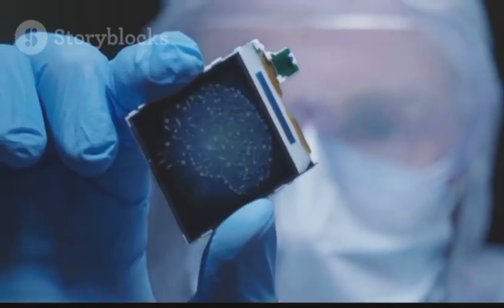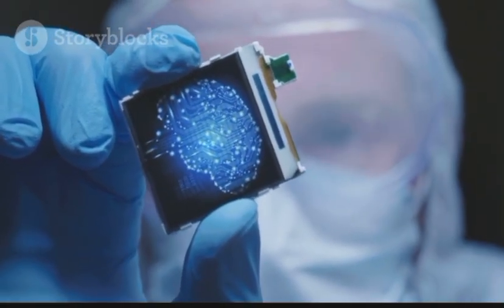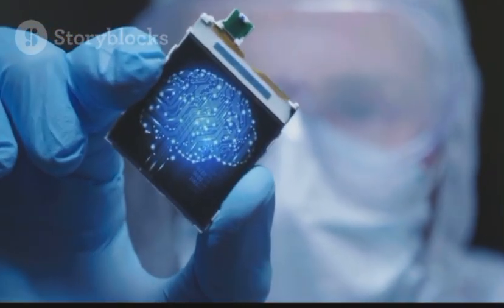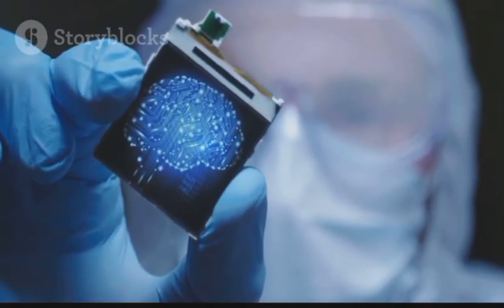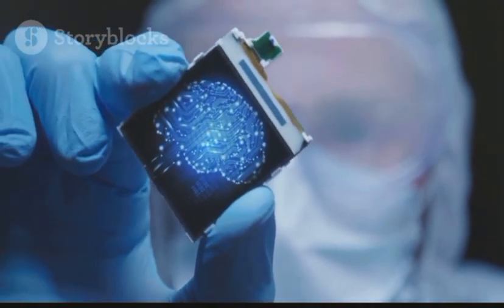This pattern guides where we add N-type and P-type elements, and where we etch tiny pathways for electrical current. This layering process is repeated over and over, building up billions of transistors and their connections. Finally, the wafer is cut into hundreds of individual chips, which are tested and packaged. From sand to a super chip, it's an amazing feat of science and engineering.